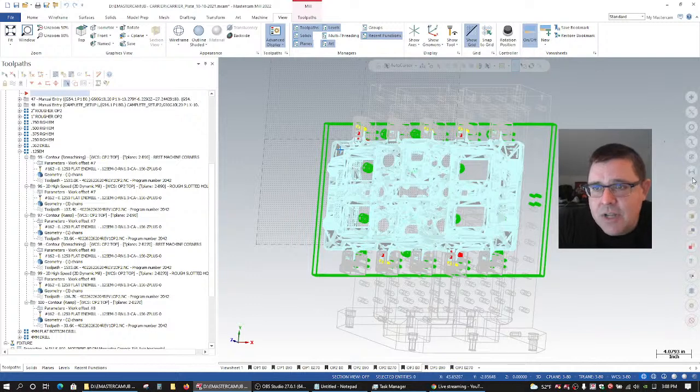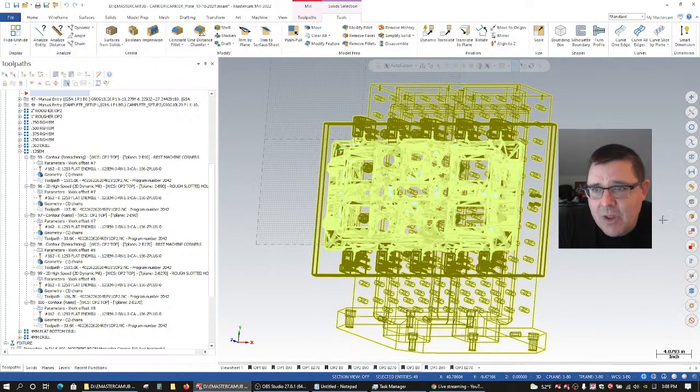So what I'm going to do is I'm going to go over to my Quick Mask toolbar, select all solid entities with the, I'm going to click on the left side of the button, not the right side. You'll notice there's a 45-degree slash line through the buttons, and the left side, upper left, is all, and the lower left is only. So if I want to put myself in only selection mode, I can do that by pressing the lower half of the button, and then going and selecting individual models. So I've selected all solids.